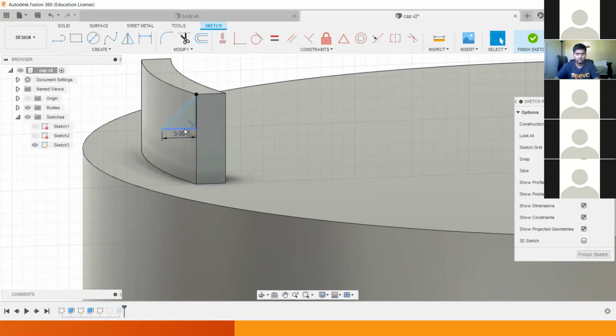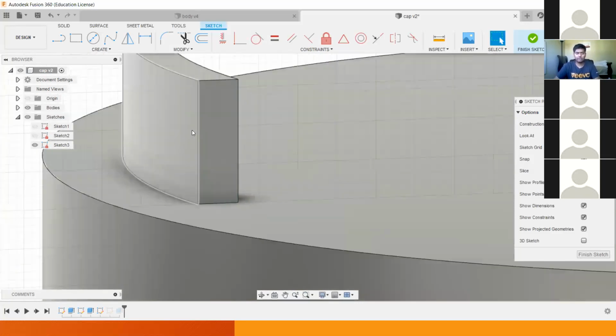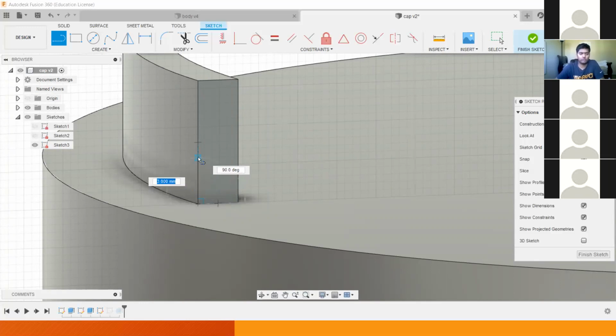Okay, so now that we've gotten rid of this, I'll redo this with you, Kyle. Thanks. So hit the line function here, and let the cursor snap to this bottom left corner, I guess. And see how it reads 5 millimeters here? Yep. We want it at 5 millimeters, so that's going to be our first line. And now we're going to create another line. Click again. We're still using the line tool, so this snaps to 3.125 millimeters, which is kind of annoying.